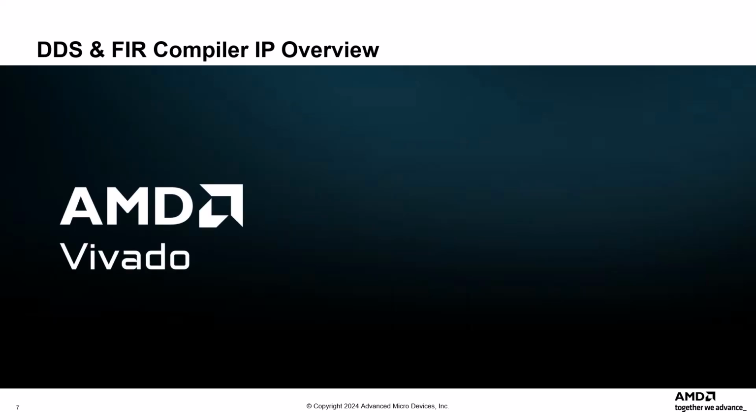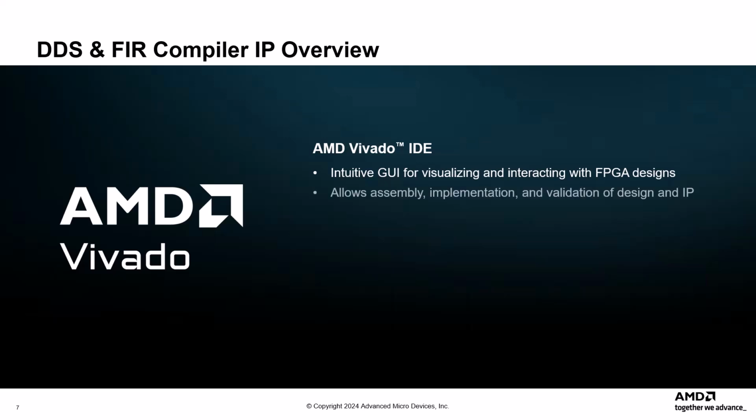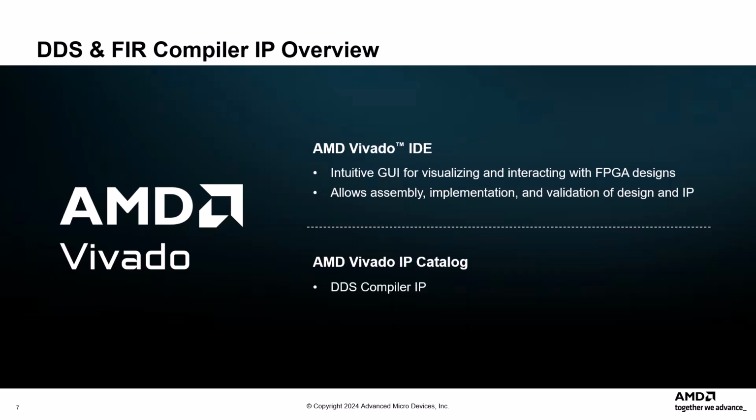The AMD Vivado Integrated Design Environment offers an intuitive graphical user interface for visualizing and interacting with FPGA designs. This interface allows you to assemble, implement, and validate your design and intellectual property, IP. The design used in this demo will utilize two specific IP blocks from the Vivado IP catalog: the DDS compiler IP and the FIR compiler IP.